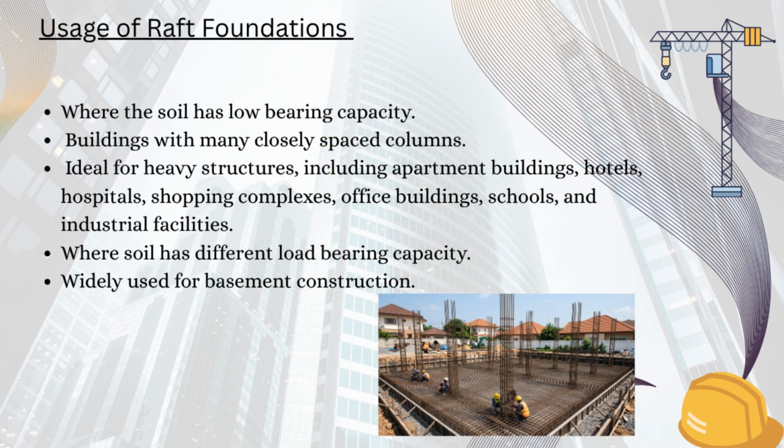Where are raft foundations used? Raft foundations are commonly used in several situations. The first is where the soil has low bearing capacity. If the ground cannot safely support isolated pad or strip footings, a raft foundation spreads the load over a much larger area, reducing soil pressure. The second application is for buildings with many closely spaced columns. Instead of constructing dozens of overlapping pad footings, engineers design one continuous raft foundation, making construction more practical and economical.